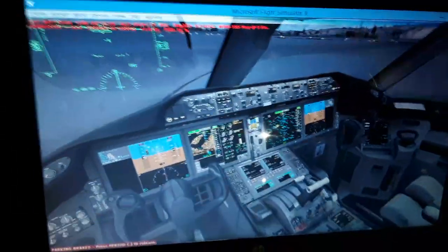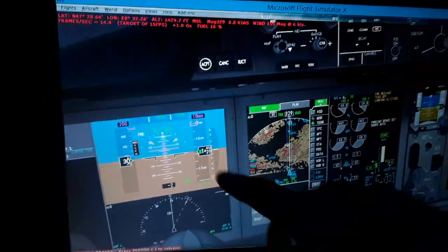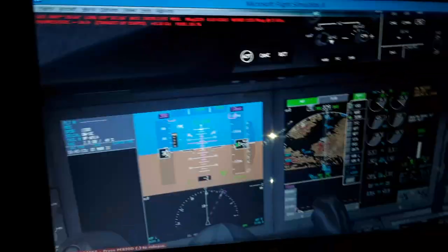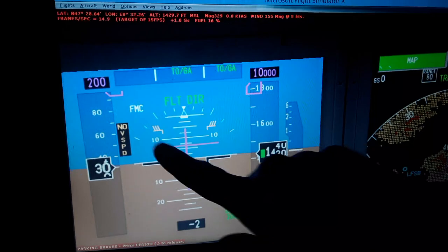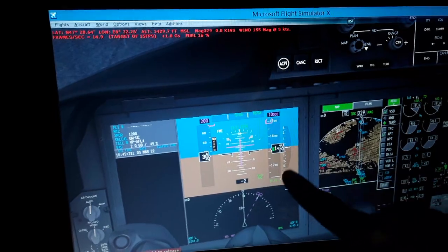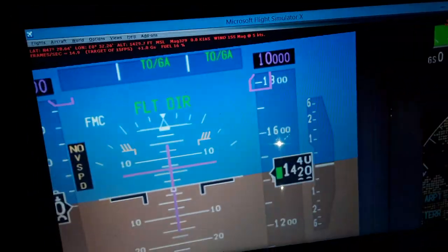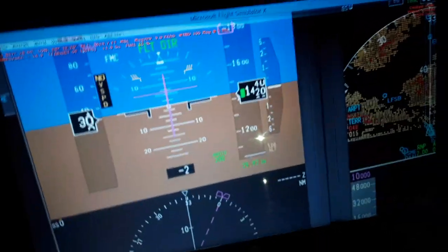We're going to have the airflow over the top surface of the wings become detached. So we have to pay attention over here. In the primary flight display, the indicated airspeed should always be above the stall speed. So you see the stall speed with red and yellow indication below the airspeed. You can see also the altitude, the target airspeed selected from your autopilot flight director system panel, the target altitude, the pitch ladder in degrees, the bank angle as we fly, how steeply we bank, and also here you can see the rate of climb or descent of the aircraft in tens, hundreds, thousands of feet per minute, or the trigonometric angles in degrees we can climb or descend.